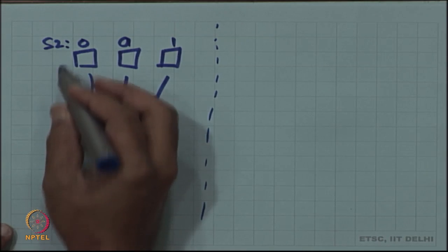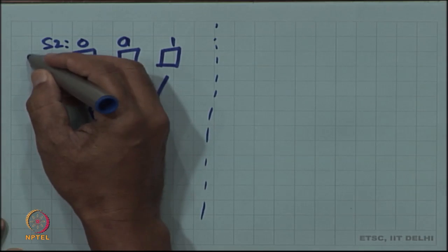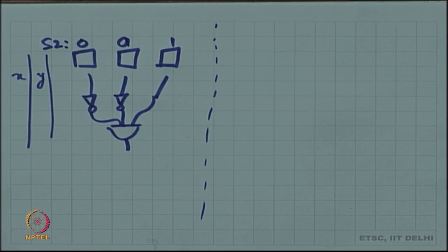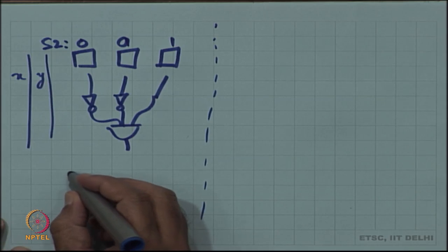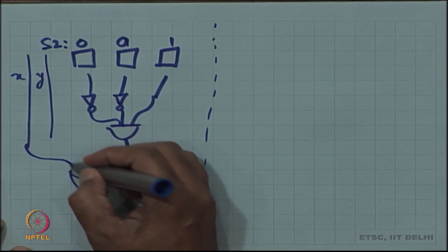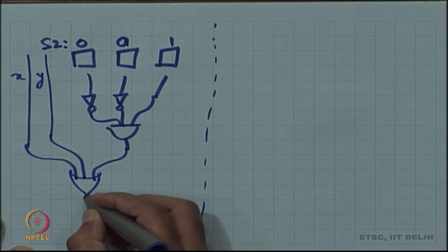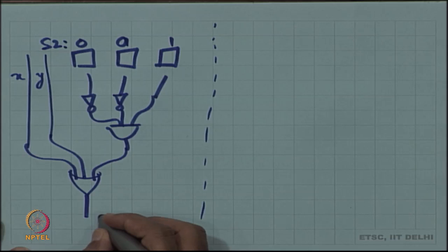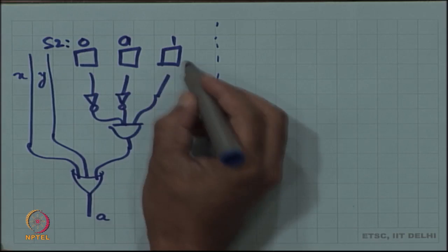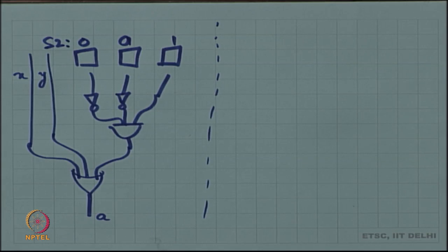This is not the only thing. In fact, there are maybe a couple of other inputs. These are the primary inputs x and y, and that transition could be that maybe you have an OR gate. If you are in that state and either x is 1 or y is 1, then the output is something. Let us say that is my logic. If I use a minimum width encoding of 3 bits, maybe my design had 7 states. So, instead of 3 flip flops, maybe I could have used 7 flip flops.